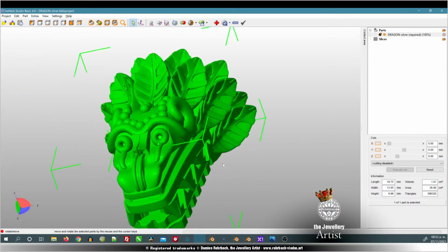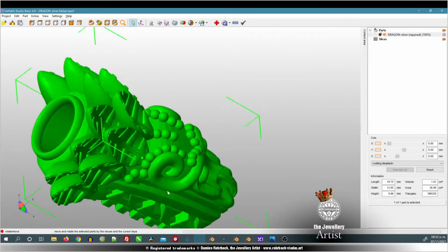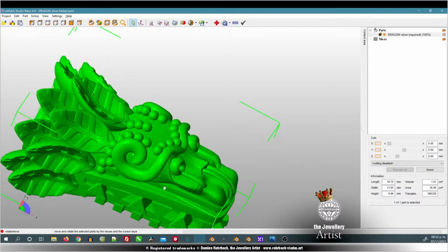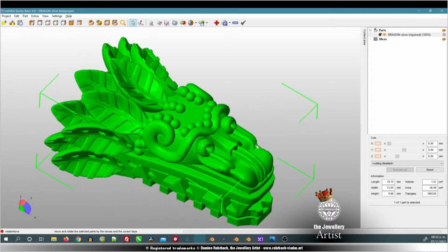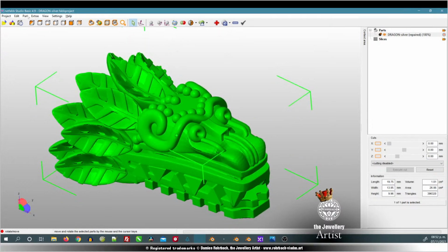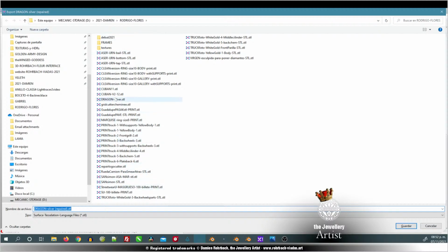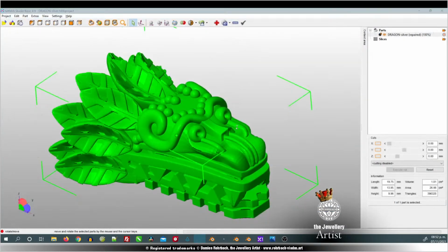the faces are clean, all the objects are solid and properly closed. The intersection between solids, they're fully completed, so you should never have just one face overlapping another face. One solid must be inside the other solid, and then you get this. It's very easy to repair. This was repaired in something like 10 seconds. And let's go back to exporting and saving the repaired file.